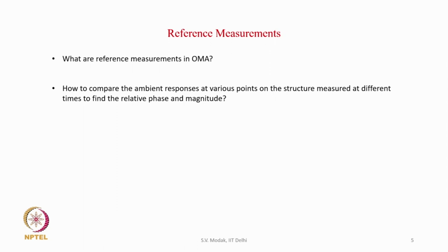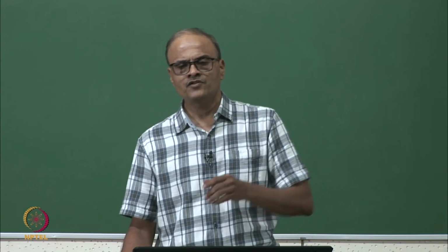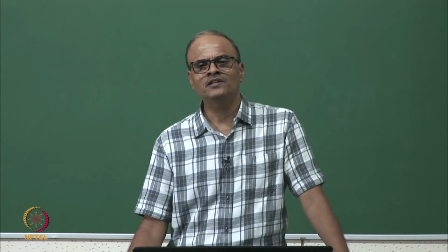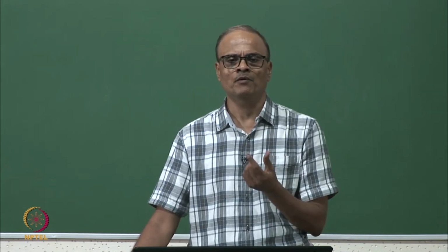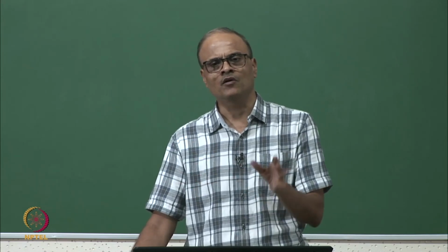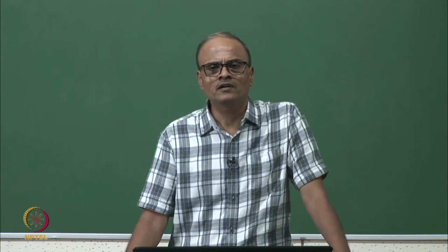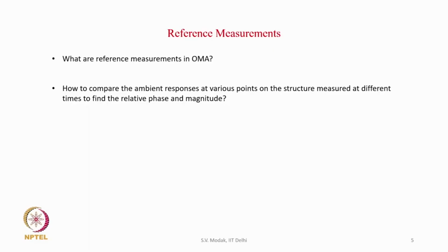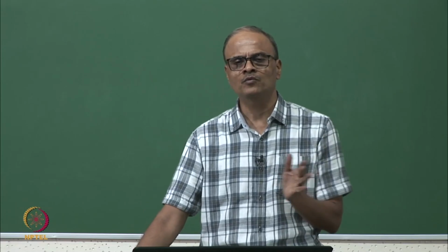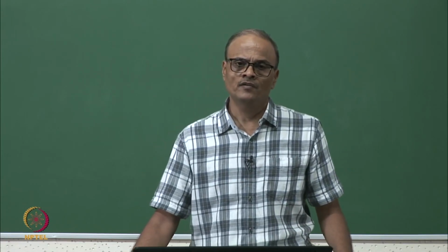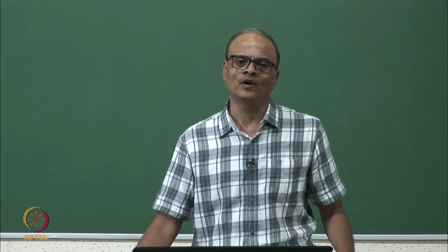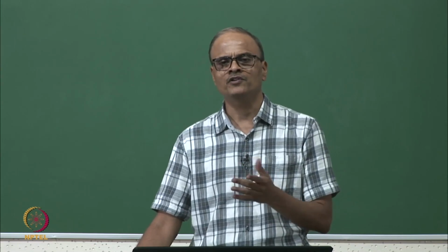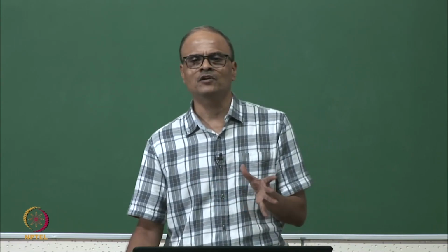So, in operational analysis we measure only the output responses, and generally for a large structure the responses may have to be measured at a large number of points. So, generally the measurements are taken in batches. We take measurements at a certain number of points and then repeat the process to complete measurements at all the points. Therefore, measurements taken at different instants of time correspond to different states of motion of the structure. Also, the excitation which would correspond to these measurements would in general be different, and therefore, these measurements cannot be directly compared to find a relative phase between vibration at different points, right. So, the relative phase and magnitude of vibration at different points cannot be obtained by direct comparison of these responses.